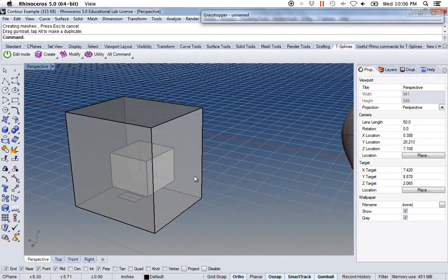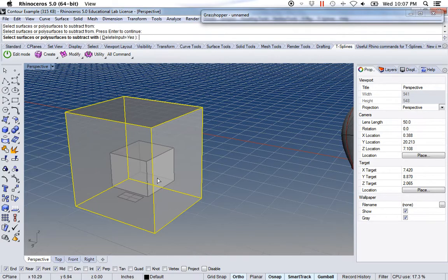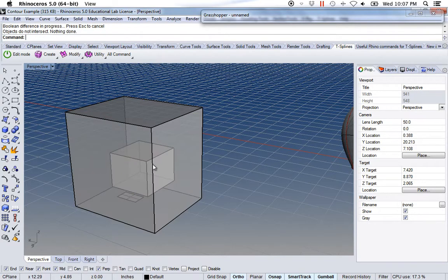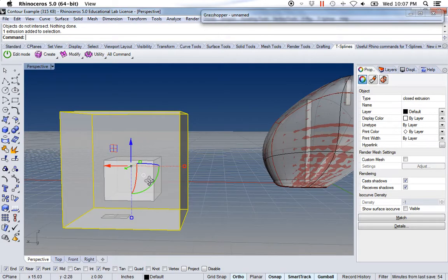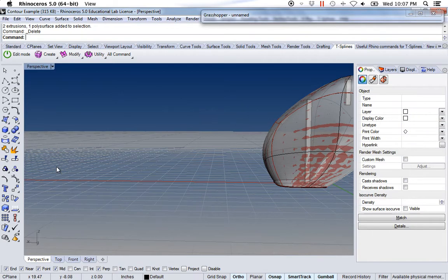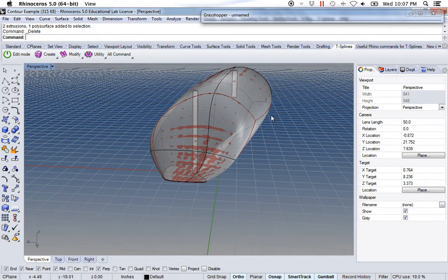And it's just floating there. If I try, even as a Rhino command, if I try to do a difference, it just won't allow it. And the main reason why, it's as if there's a shoebox and then there's another shoebox floating on the inside. And there's really nothing to make a difference of. So that's the only trick with trying to make this into a difference.